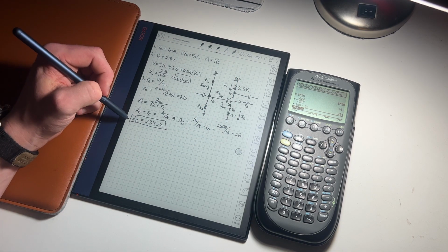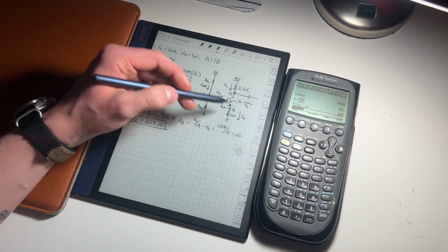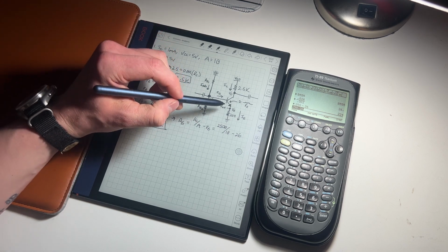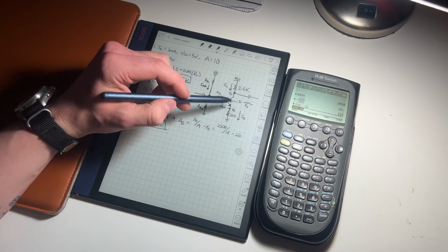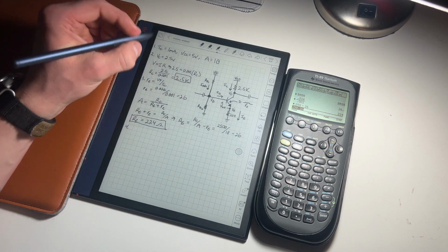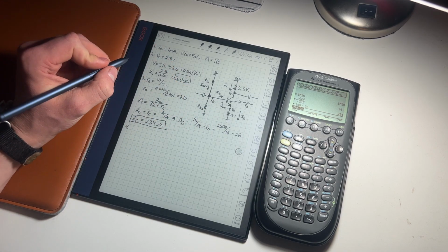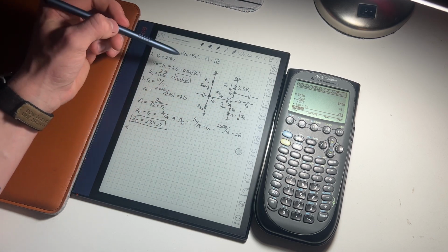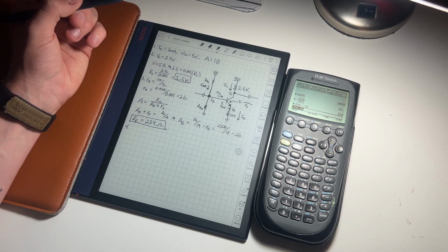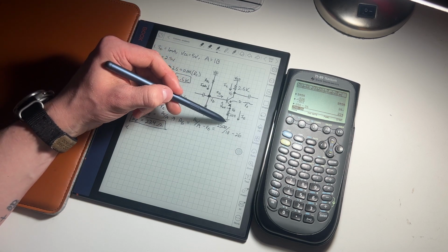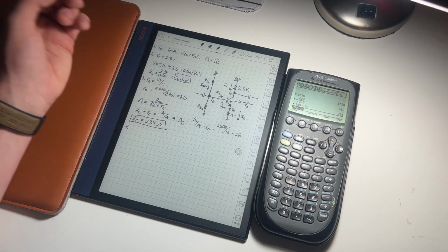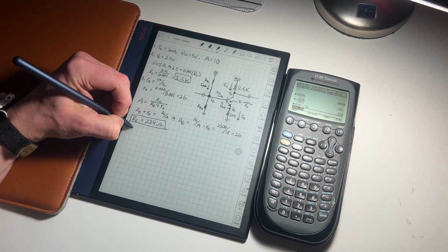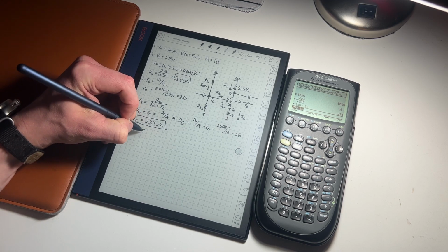Now that we have the value of big R sub E, step 4 is to actually determine the voltage on top of the emitter resistor. We can do that using Ohm's law and the fact that I sub E is roughly equal to I sub C because the base current contribution is very small. So again, this is just a basic Ohm's law problem. V equals IR.